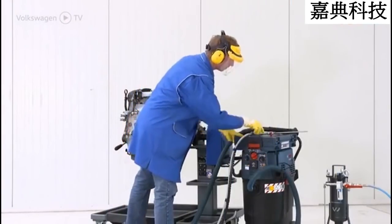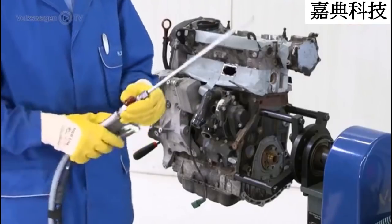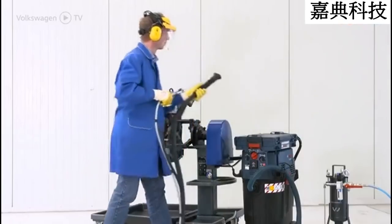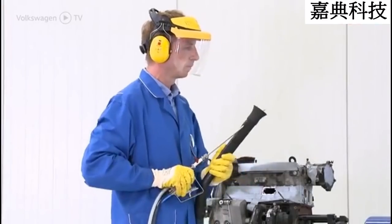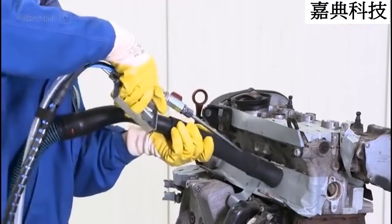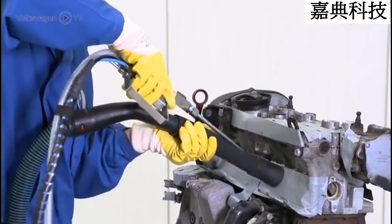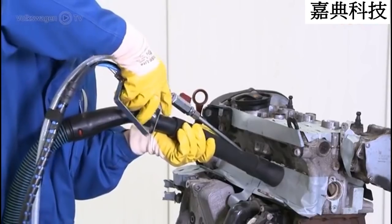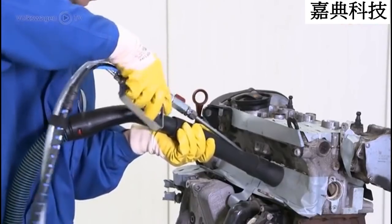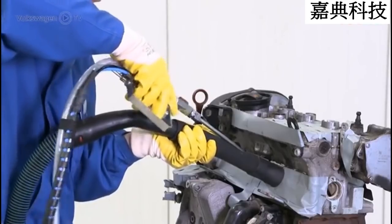Switch on the vacuum cleaner. Open the lance's shut-off valve. Insert the lance into the extraction hose of the granulate blasting unit. Attach the extraction hose flush to the cylinder head's inlet duct. To clean the valve stem and the valve plate, repeatedly turn the lance and move it in and out.